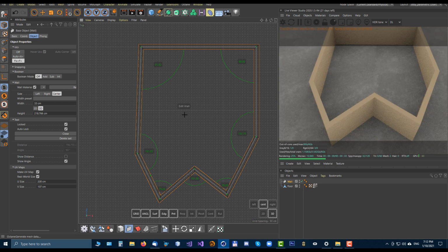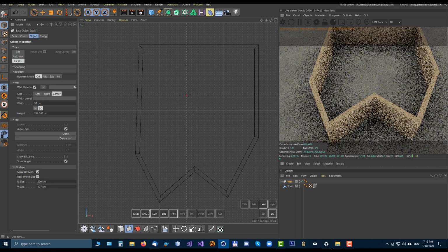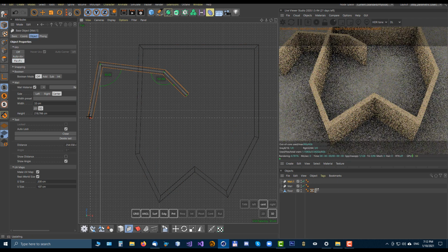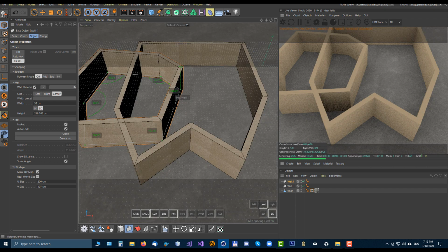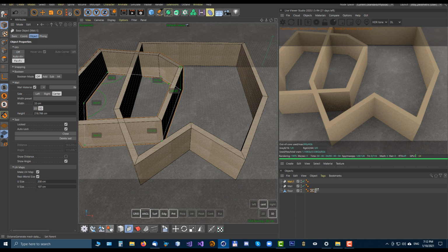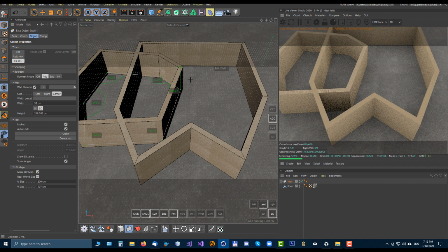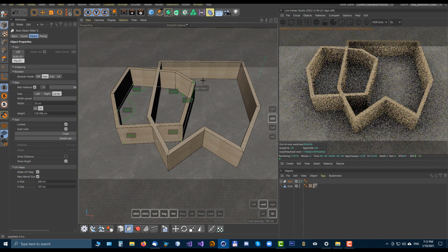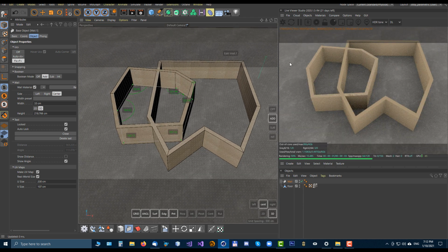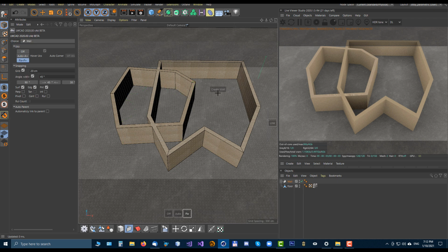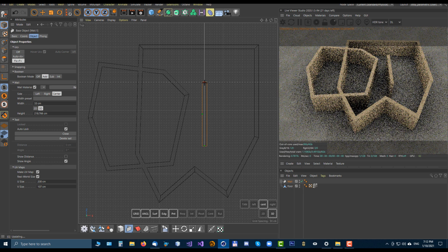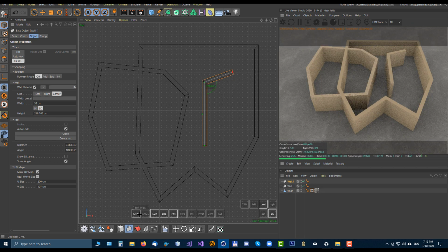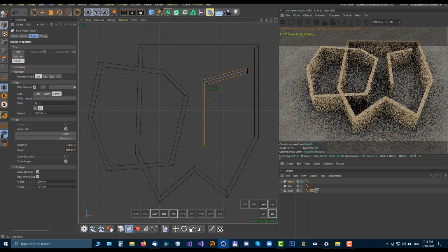And because this is a primitive, you can create another wall, attach it to the previous wall and use Booleans, and you create one single wall from two walls very easily. One more very nice feature of the wall, I will disable all this, is also end tangents.